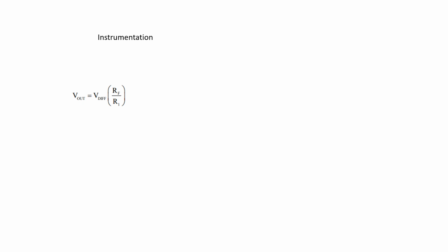Okay, so this is a difference amp, so it's quite easy. One with the 4 resistors. Yeah, you've got it. I think you need that one. Look at that. I'm a really bad drawing. That one there. One goes to 0. And then one loops round. Okay, so basically it's V diff times gain equals V out.